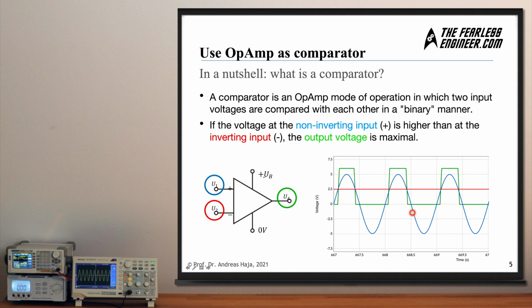Now we want to simulate this switching circuit and use it to trigger on and off an LED which is powered by a transistor. And in case you're wondering why we need a transistor, we don't actually need it in order to simply switch on an LED, but we can use the operational amplifier to trigger a transistor-based switching circuit which can switch on and off much more than a simple light-emitting diode. So this lays the groundwork for switching on and off stuff, let's say a motor or a relay, which can be done with an operational amplifier in this switching stage. Now let's head over to Tinkercad to see how we can construct such a thing.